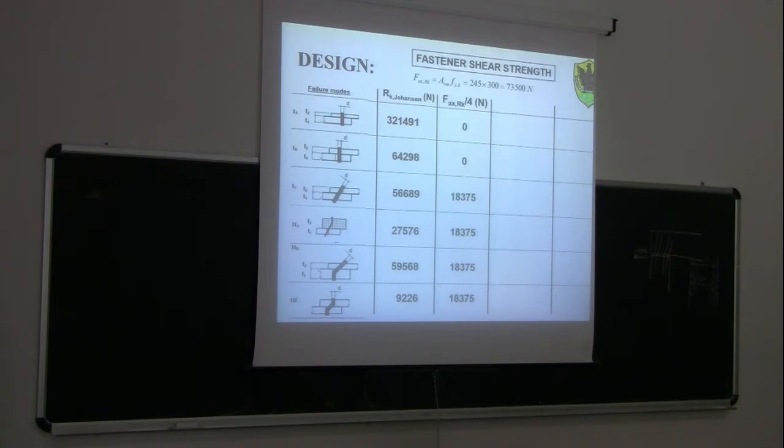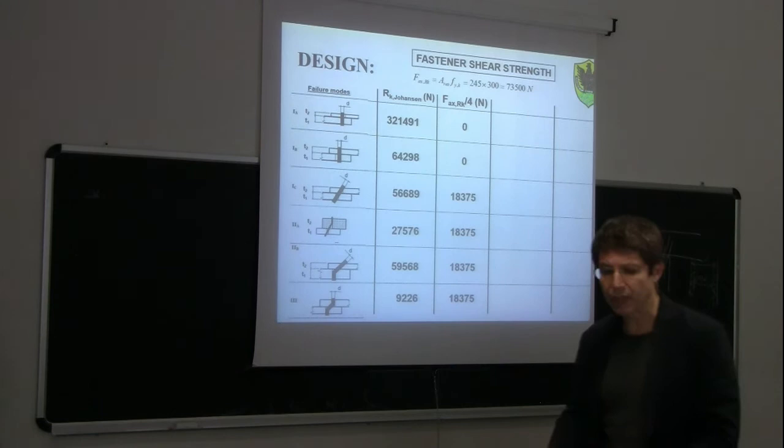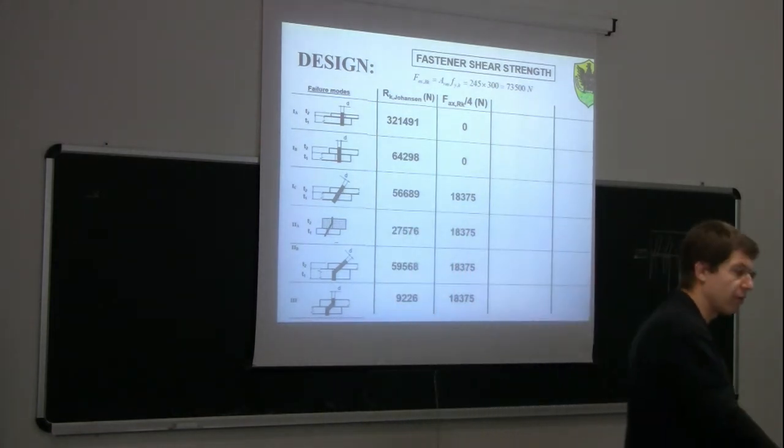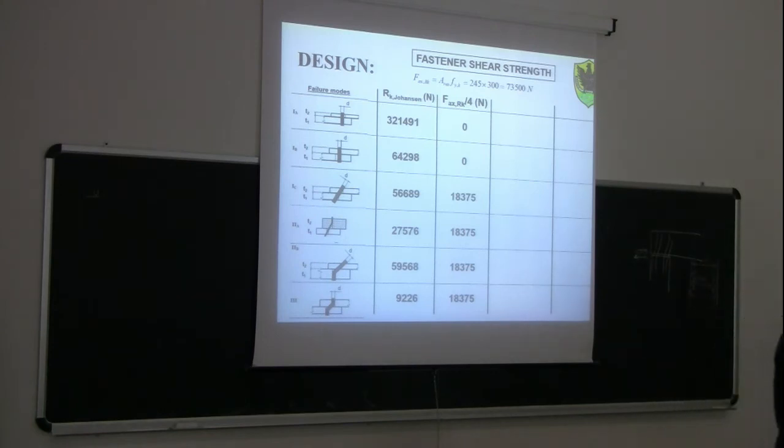Then we calculate the rod effect, which is 1/4 of the withdrawal capacity. The withdrawal capacity is calculated using this relationship here. If you remember well, we designed the rod in order to make sure that the rod will yield before having a failure for bonds or a failure to move. If you remember, we applied this 1.5 coefficient yesterday.